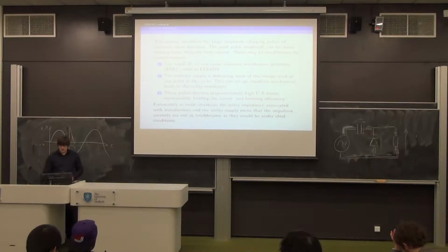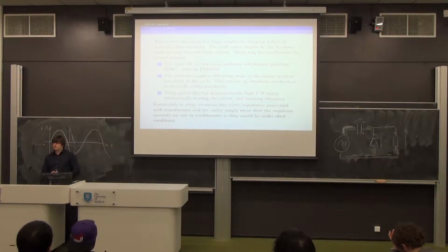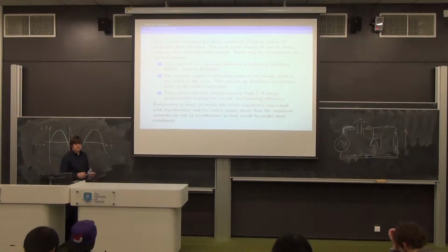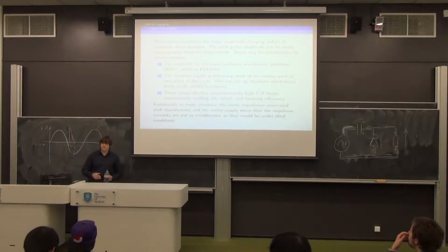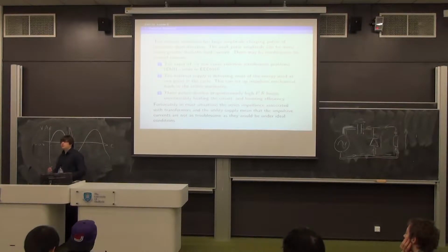And this rapid change in current can cause some problems, because if you have a sudden di/dt, what you end up with is lots and lots of high frequencies. Eventually you will come onto a kind of analysis that allows you to go between time and frequency domain, and when you do you'll find out that fast changes in voltage and current lead to high frequencies existing.